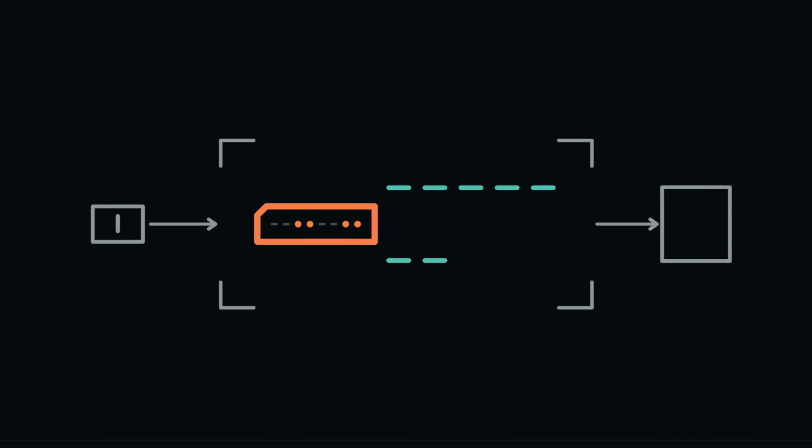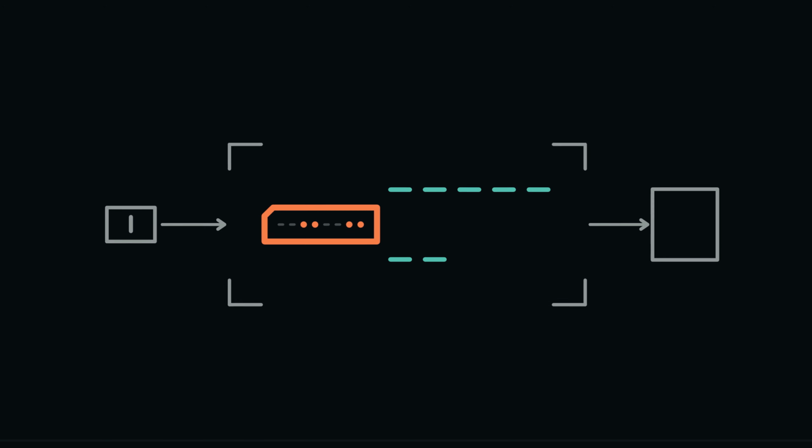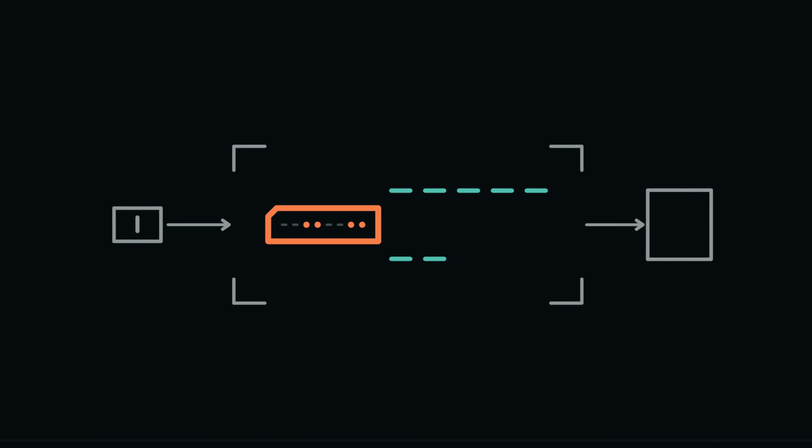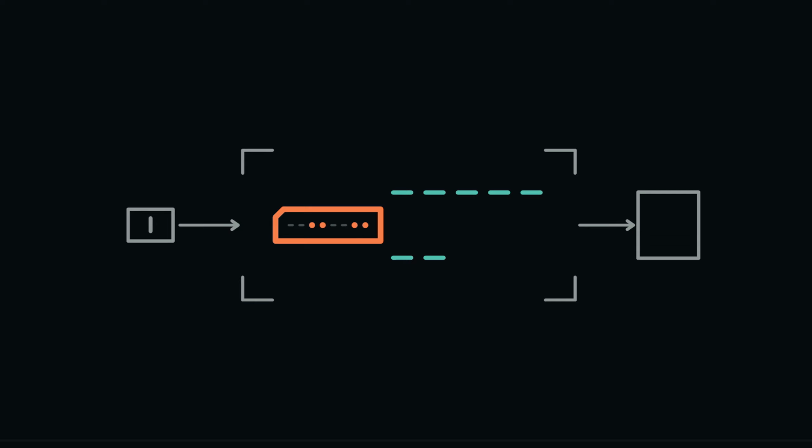Show the whole operation before opening it. R0 begins at 3. PC points to hexadecimal 20, where memory holds the 2-byte instruction subtract immediate from R0, 01 6. Fetch edges collect the 2 bytes. 1 execute edge subtracts 1 and commits 2 to R0. PC finishes at hexadecimal 22, ready for the next instruction. That is the complete promise.